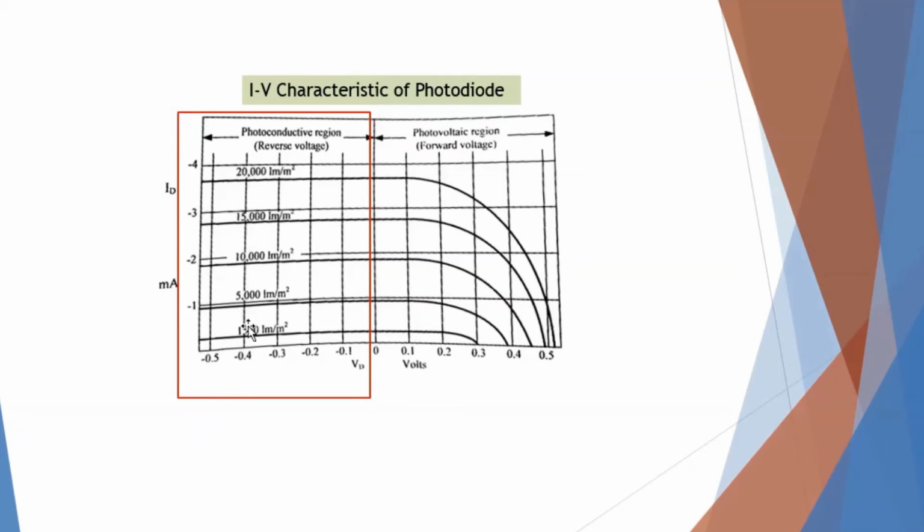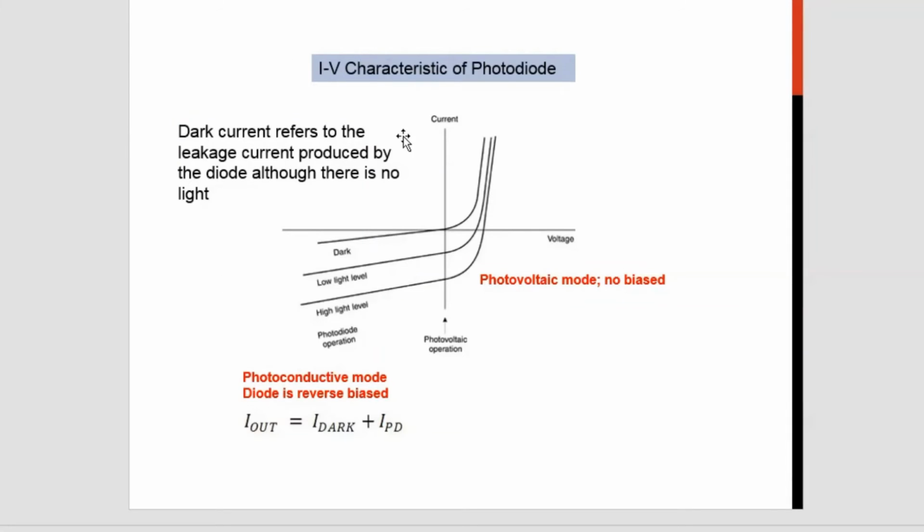These numbers here are the light intensity. It will provide constant current, but the voltages will vary. Okay. In your slide, it shows something like this, which is also the same, and almost constant current with varying values of your voltage. Okay. So at higher light levels, it will have a higher current.